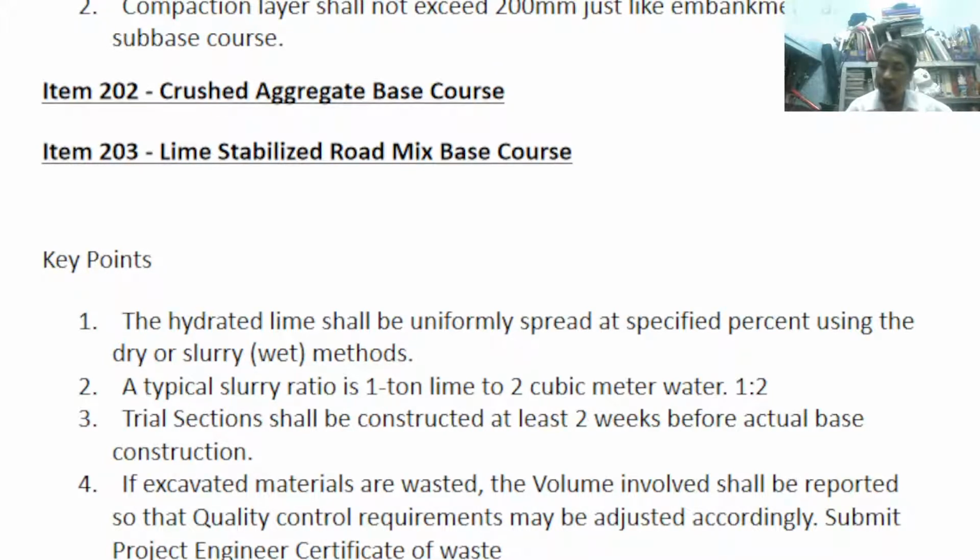If the road is already moist with water, you can use a dry distribution of cement all along the proposed road. It will become paste, reacting with water and bonding the different sizes of particles in its vicinity.